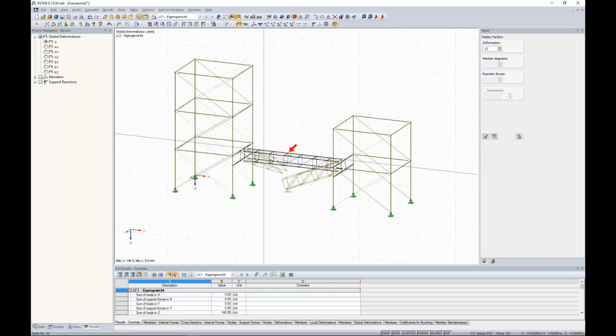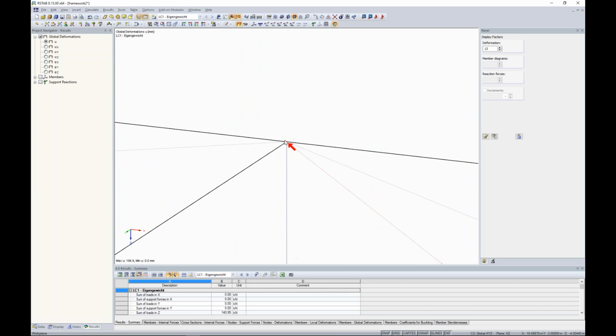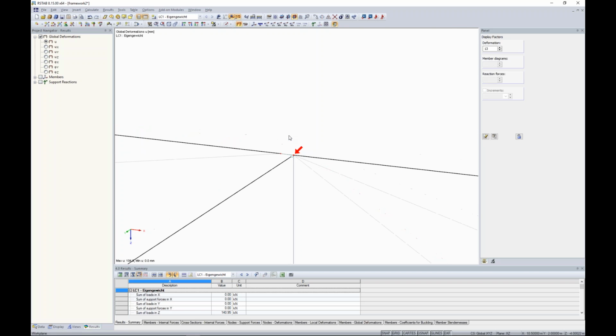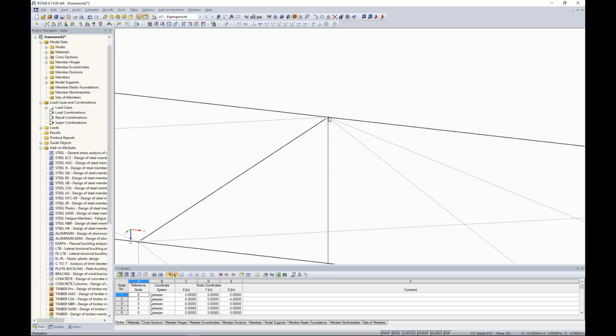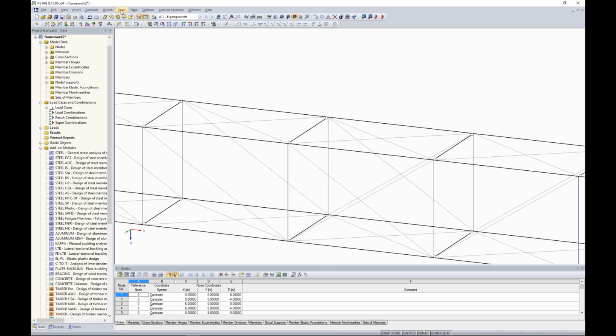You get an information error in the graphic, and if you zoom in, it still looks connected, but in the end, you can see that there's a problem. These are not connected, and I can just drag and drop this one, or you can use the check again with tools, model check, identical nodes.